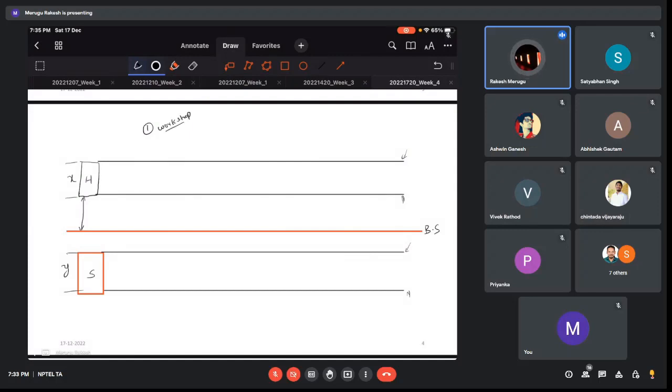In these gauges the philosophy is like this: the workers believe that everything is made correct, so there is no wrong product made by them. Based upon this principle, the gauge tolerance will be inside the actual tolerance value.